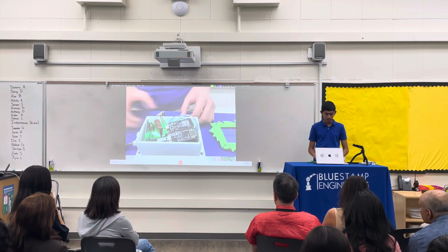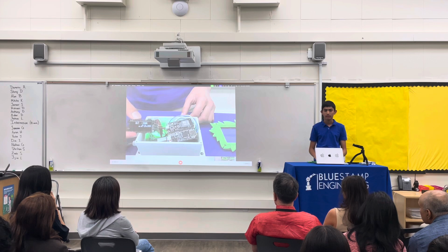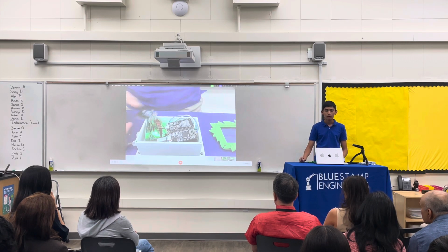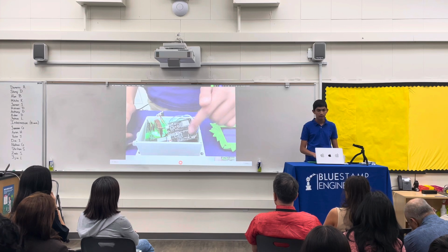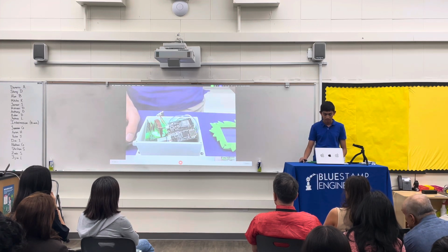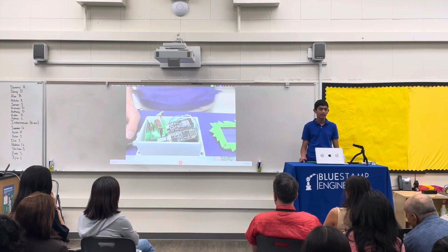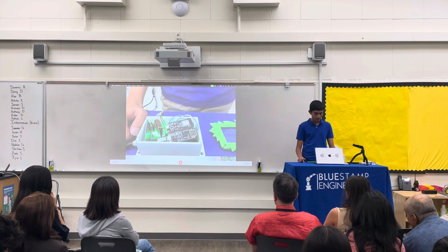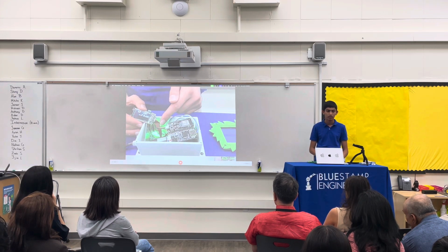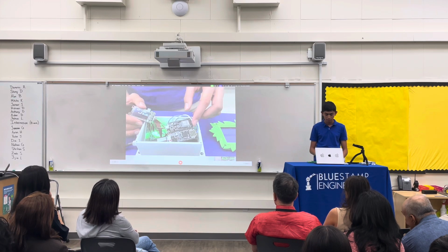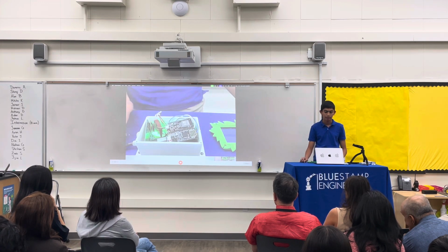After that, it took me to another challenge, which was adding the OLED screen. When I added the OLED screen, I wired it directly to the Feather M4 Express. This caused a power issue, and it could not connect to Adafruit.io anymore. To fix this, I had to desolder everything, and I connected it via STEMMA QT wires, which is way cleaner than regular soldering.